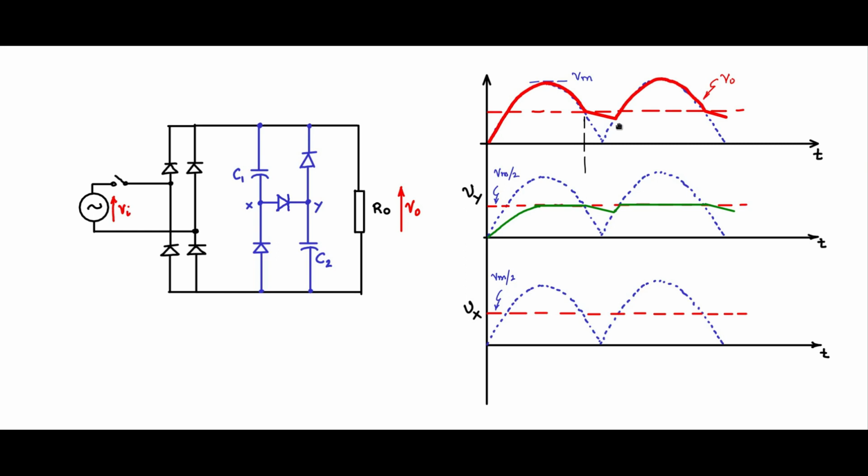So this is V0. So let me draw these critical marker points like that. So during this time only the current is 0 here. This current I is 0 here because at that time the capacitor is discharging. And during this time you will have the current, this first cycle charge, it is like this. The second cycle onwards you will see that it will just be in this fashion. Now you see that the conduction period of this current has been widened so much, and therefore the peak would be significantly lower compared to the normal capacitor rectified filter capacitor circuit.